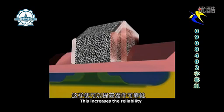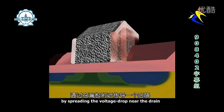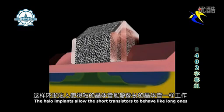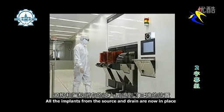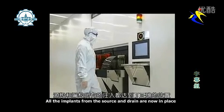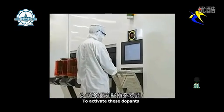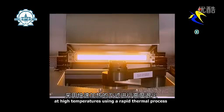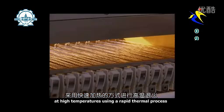This increases the reliability by spreading the voltage drop near the drain. The halo implants allow the short transistors to behave like long ones. All the implants for the source and drain are now in place. To activate these dopants, the wafers undergo annealing at high temperatures using a rapid thermal process.